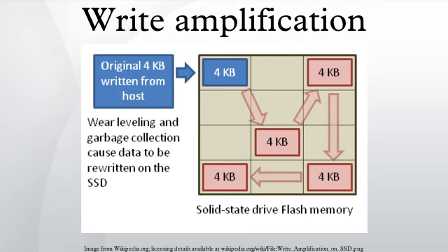This is often referred to as the maximum number of program erase cycles it can sustain over the life of the flash memory. Single-level cell flash, designed for higher performance and longer endurance, can typically operate between 50,000 and 100,000 cycles. As of 2011, multi-level cell flash is designed for lower-cost applications and has a greatly reduced cycle count of typically between 3,000 and 5,000.